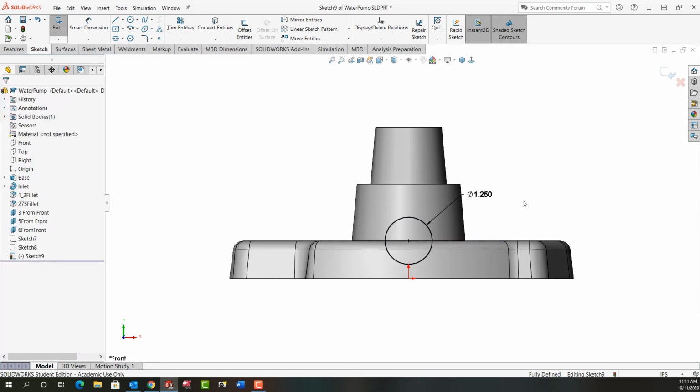Now because I'm creating a loft, each sketch of the loft must have the same number of entities on it. So he's going to have us split this circle into 4 entities. However, a circle has an infinite number of entities and should work fine in the loft. But I do want to demonstrate this, so I'm going to use the split entities command next.